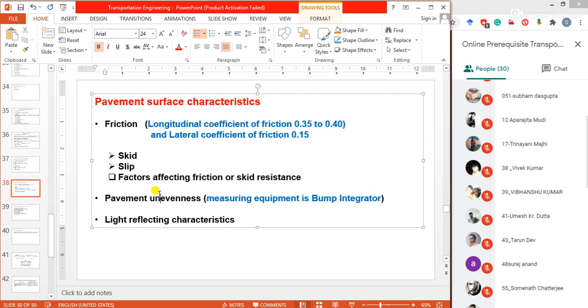While a vehicle negotiates a horizontal curve, if the centrifugal force is greater than the counter-attracting forces, that is lateral friction and the component of gravity due to super elevation, lateral skidding takes place. Lateral skid is considered dangerous as the vehicle goes out of control, leading to an accident. The maximum lateral skid coefficient is generally equal or slightly higher than the forward skid coefficient in the braking test.